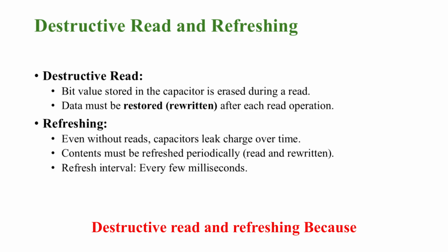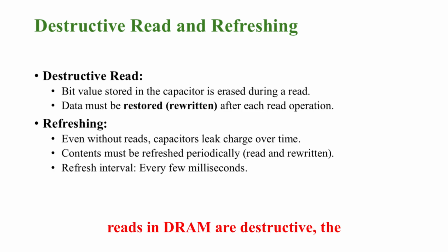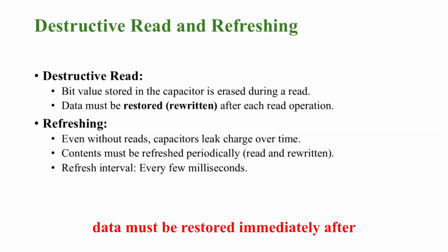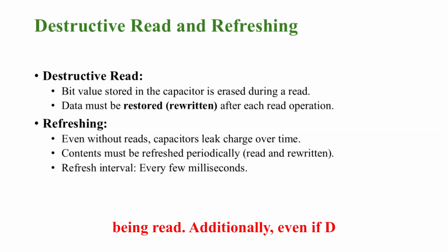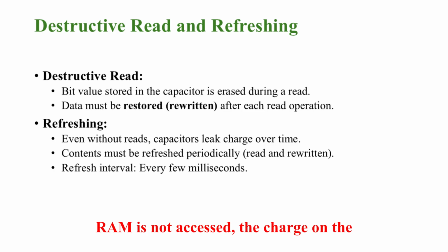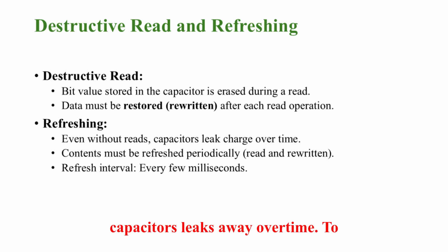Destructive read and refreshing. Because reads in DRAM are destructive, the data must be restored immediately after being read. Additionally, even if DRAM is not accessed, the charge on the capacitors leaks away over time. To prevent data loss, the contents must be periodically refreshed, which involves reading and rewriting every cell in the memory array. This refresh process occurs every few milliseconds, ensuring that data integrity is maintained.